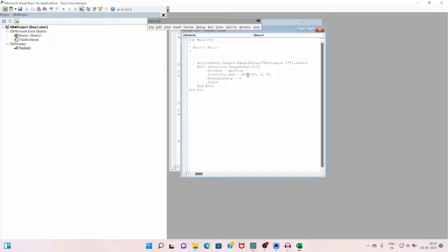Similarly, what we get in our STAAD editor file with a star, we call it a comment. STAAD will not read those lines. In the same fashion, in VBA also we get the facility of commenting lines, which can be used for information about the programming, for what purpose the line below is written, or whatever you want to write, you can write with these green lines.